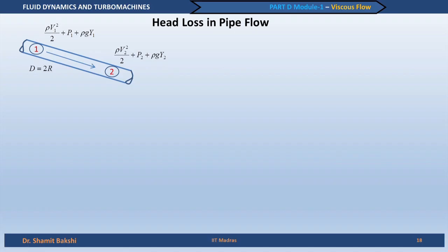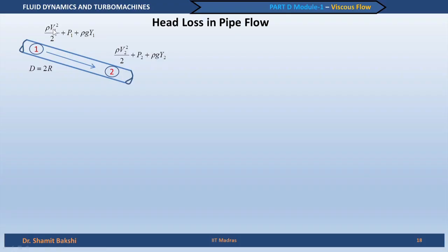See, that is why we got an expression for average velocity in the last slide, because that is what is useful when we try to estimate friction for an actual pipe. We cannot use the total velocity profile, it is too complicated. So, a simple way is to estimate the average velocity, that can be obtained by knowing the cross sectional area of the pipe and the flow rate.